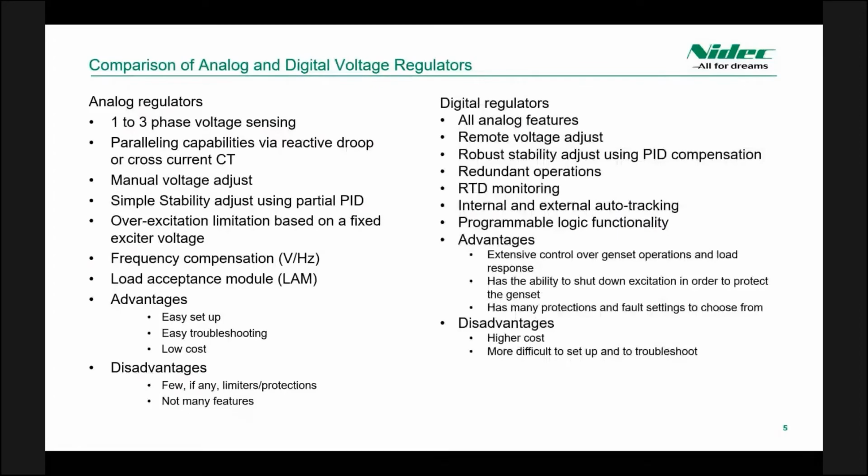Digital regulators, on the other hand, essentially do everything that an analog regulator does, but also have ways of protecting the generator and logging data associated with the generator's operations. Digital regulators come equipped with a more in-depth stability control, known as PID compensation. This allows you to adjust 3 different set points to really hone in on generator stability.